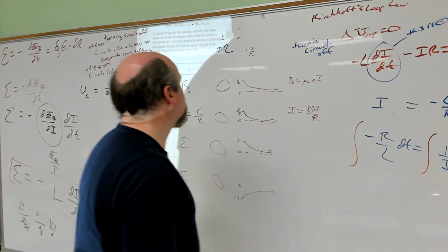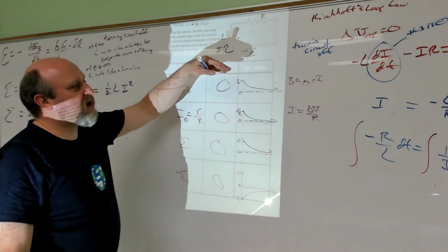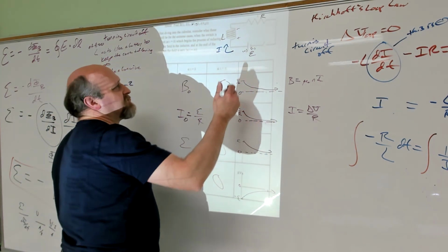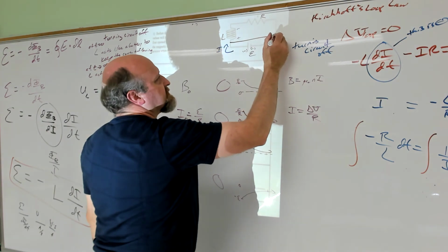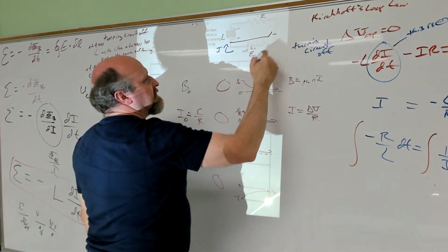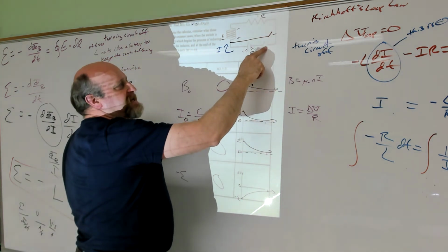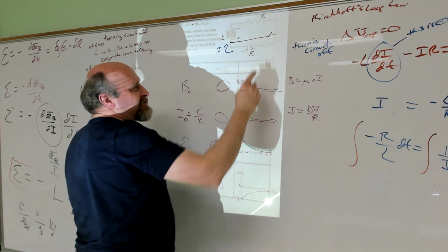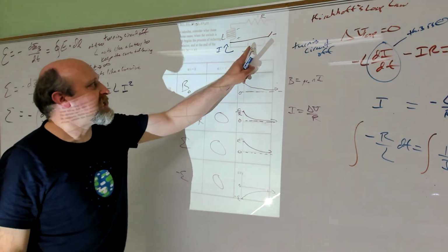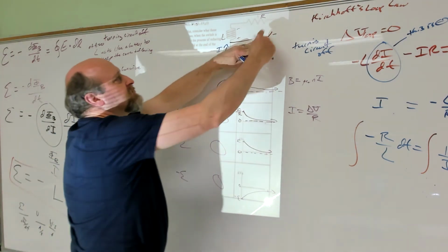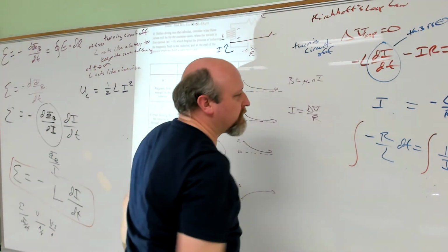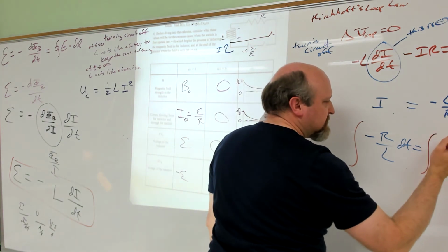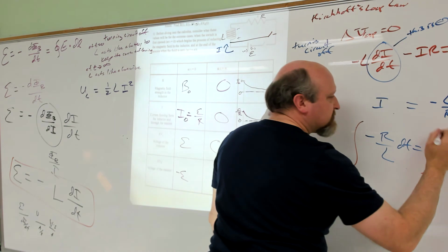In this case, I had the circuit running and I'm just turning it off. Oftentimes they'll have a circuit like this and say we simultaneously, don't ask how, close this switch and open this one. Opening this one takes the battery out of the circuit, and closing this one lets the inductor discharge around. Anyway, we go from the original current to the current at some point in time.